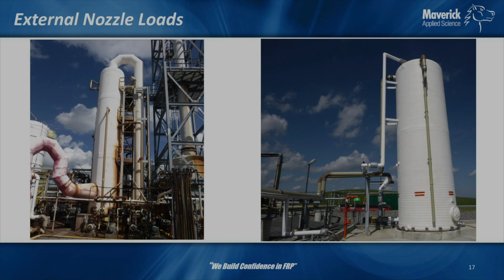This is where that construction comes in, is that you have hand layup. There's one thermal expansion coefficient. If it's like 55-degree wound pipe, it's a different one. 55-degree wound pipe is going to be a little bit less than hand layup. Like I mentioned earlier, oh, let me go back here. Oh, I'm going the wrong way.